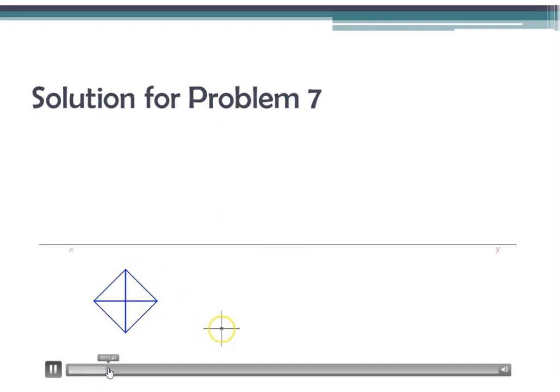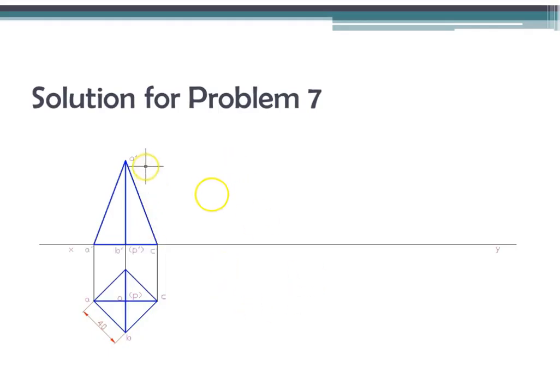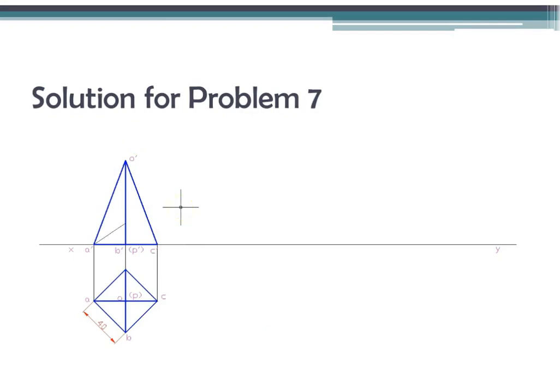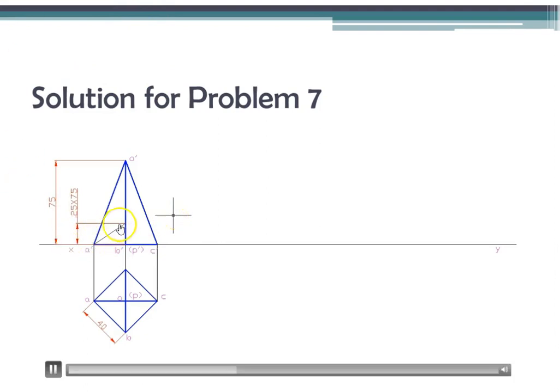So we position the square pyramid so that one of the corners is on this side. Since this is a corner which we want to use, we tilt it in such a way that we can use this base condition. And one thing you could notice is a line has been joined from one of the corners to 1/4 the height, which is the CG, which has been marked as G dash.